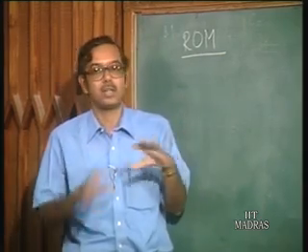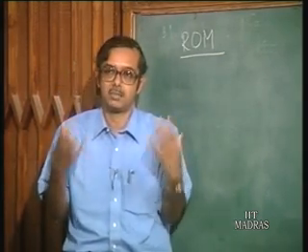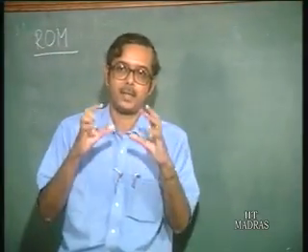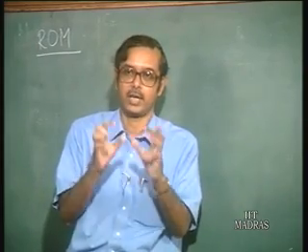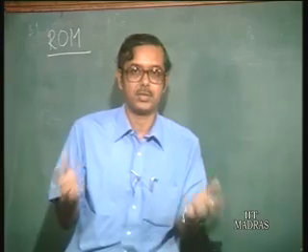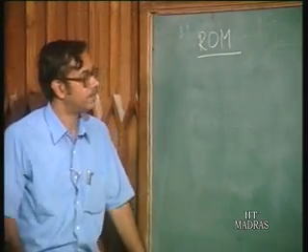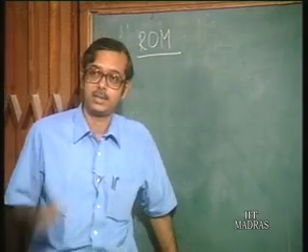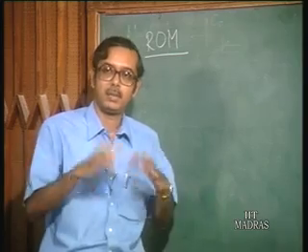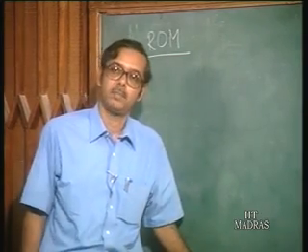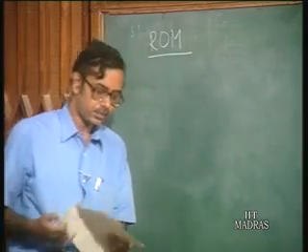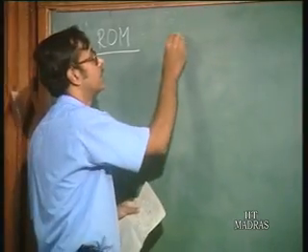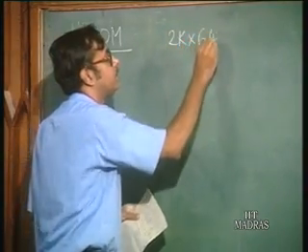Because it is read only memory, it is just meant for reading. You cannot alter the memory, whatever is stored there, and in a microprocessor, since the instructions are fixed, there is no need for changing them. So, you actually use a read only memory. So, again we just take it up and see how use of BiCMOS, that is bipolar transistors, together with again the basic CMOS environment, actually improves the performance. So, in that particular chip, the ROM they used was a 2K into 64-bit ROM.